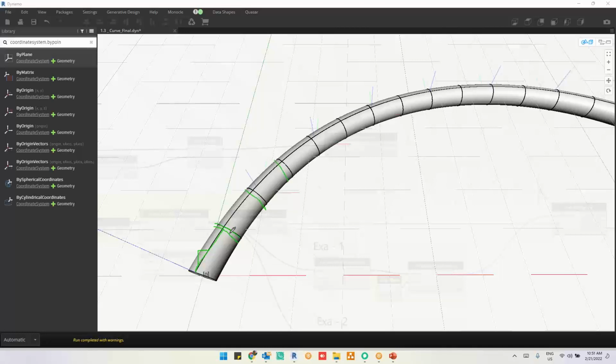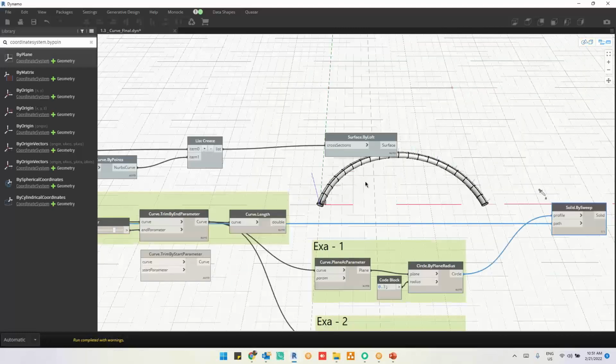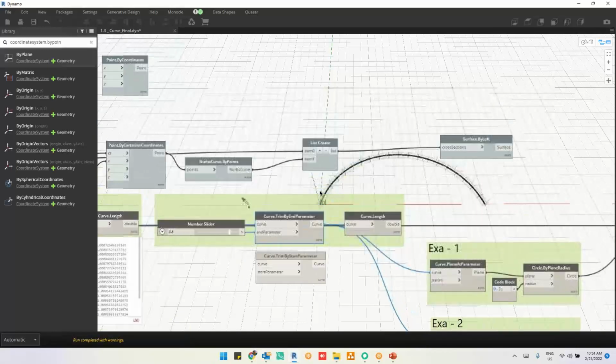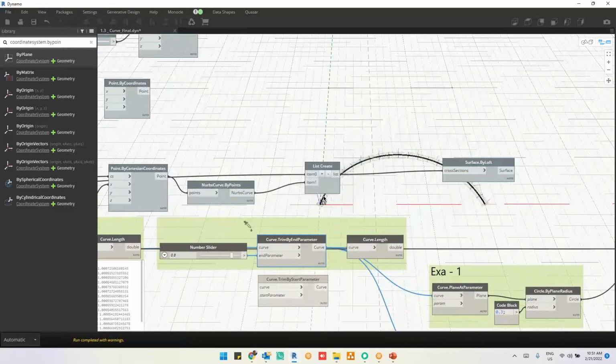How to do that? So I have a curve. I have to trim some value. I mean, I have to trim the curve. That is what I did. Erase all the drawings. Control B. So what I have done is curve trim by parameter. So just trim that here.